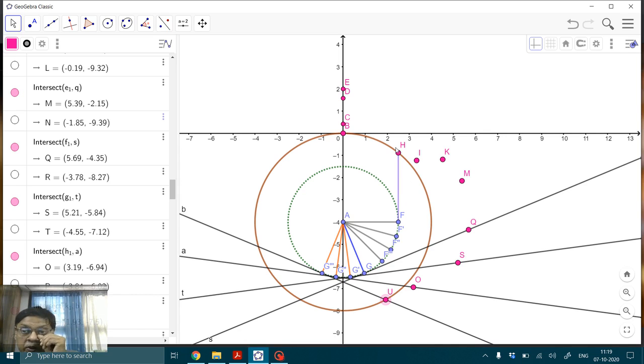FH is basically, if you look at this as a triangle, AF is the offset E, and of course AB is basically RP. So if you look at this triangle, this is going to be the offset. The height of this can be obtained from RP and E. So root of RP square minus E square is going to be the height of this FH. Please figure that out from the right angle triangle. So that is what will give the height of FH.